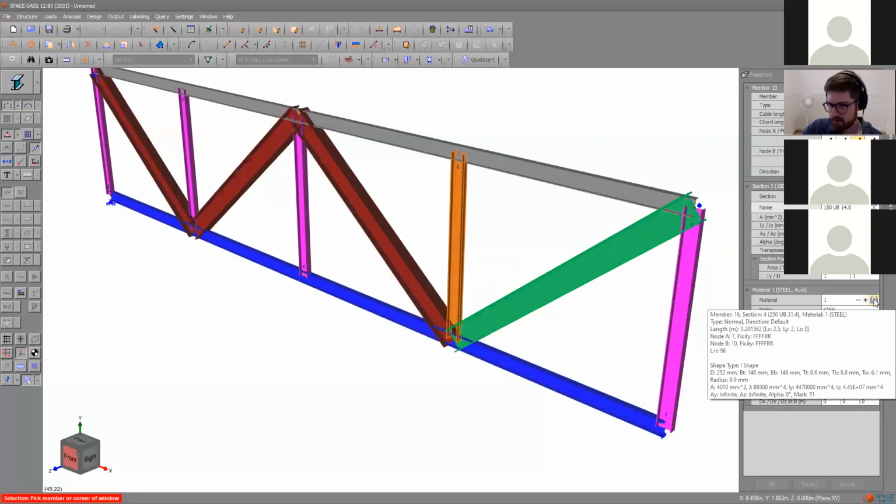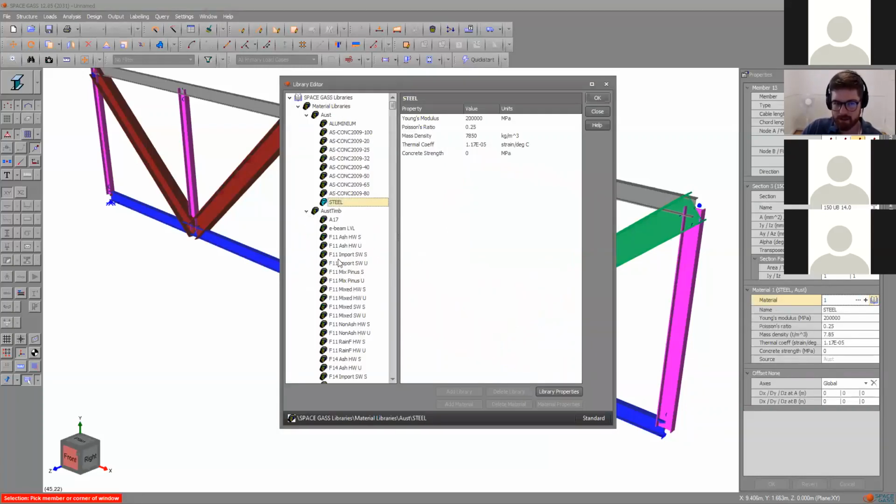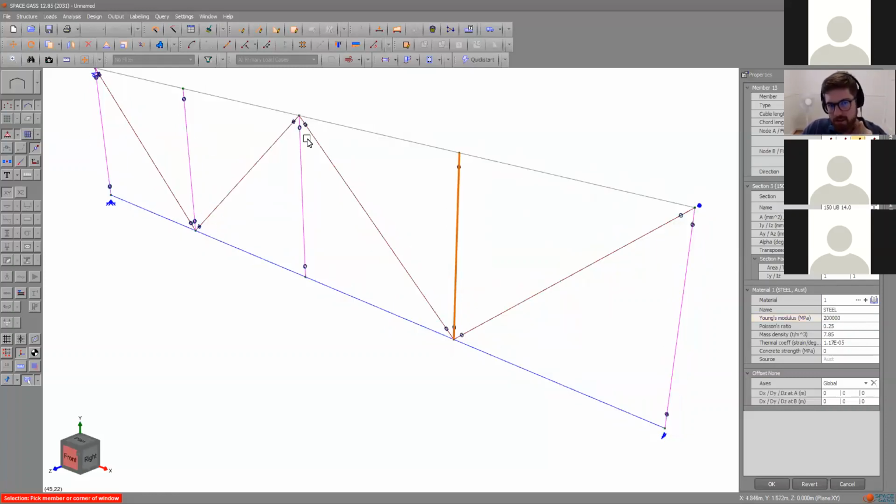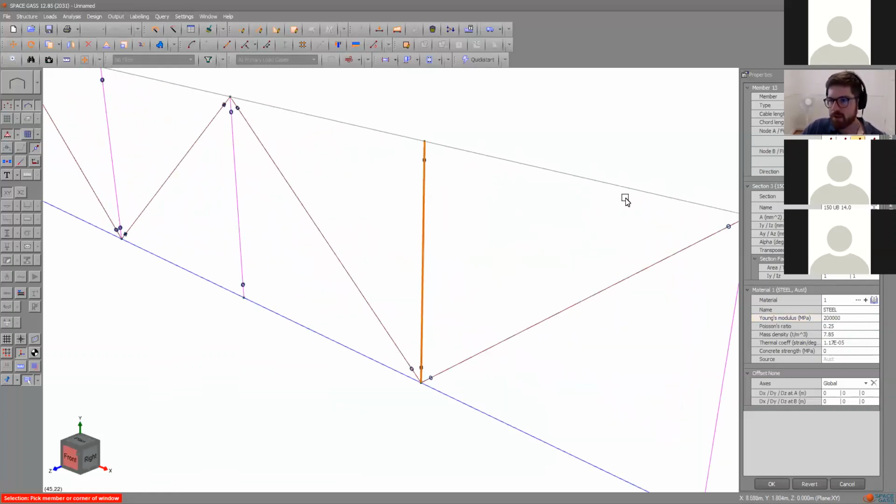In the interest of time, you can input your material properties. Steel is standard, but this has all the basics: concrete of different grades, timber, aluminium. Pay close attention to it. You can input it manually. Member fixities are the number one thing that junior structural engineers get wrong. There is no right member fixity. It depends on your connection detail.